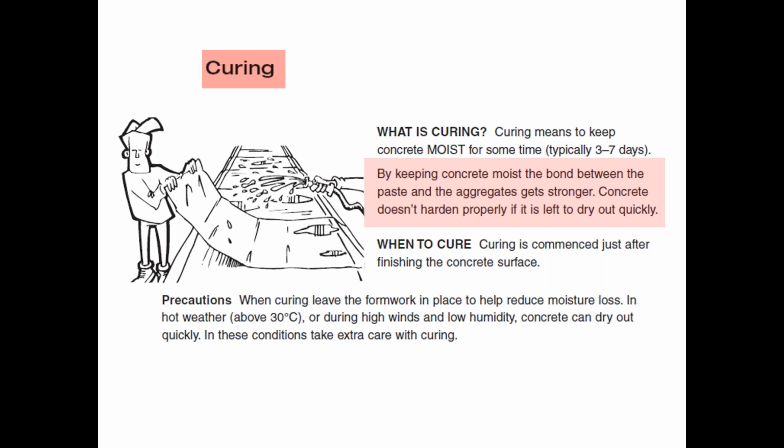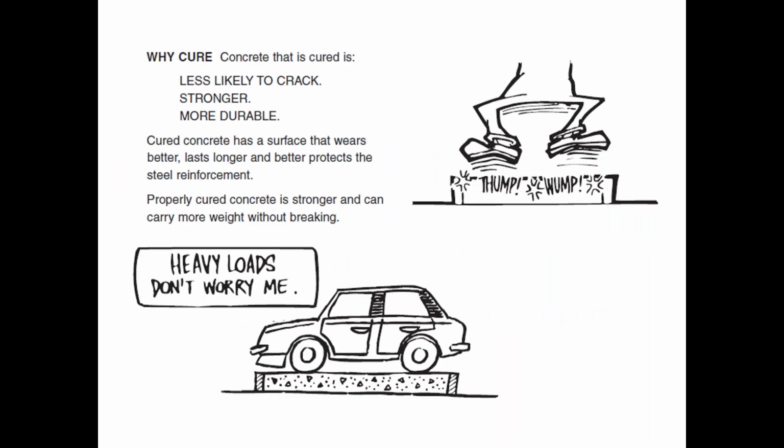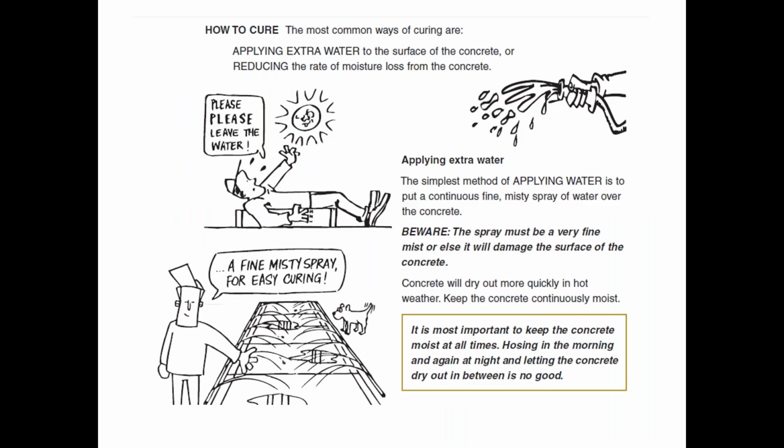When to cure is you start commencing it once you've finished doing the final finishing on the concrete. And then what it gives you is less likely to crack, it's stronger, it's more durable, and it ends up with a surface that wears better and takes higher loads, or the loads that you expected in the first place. When you order concrete, you order it by the strength, and you want to get that strength. In order to get that strength, you've got to cure it properly as well.